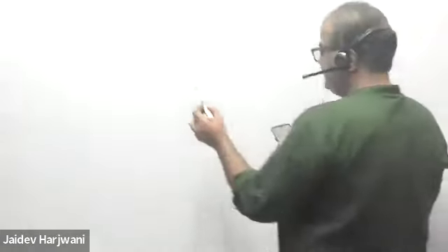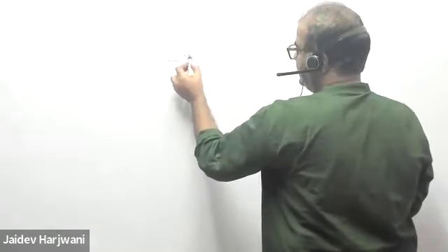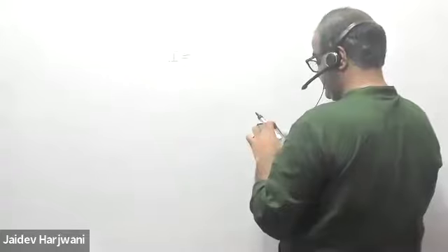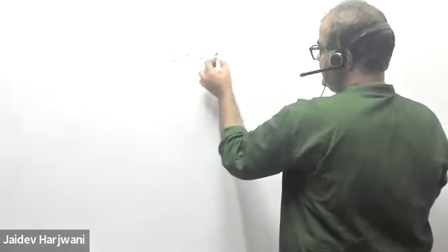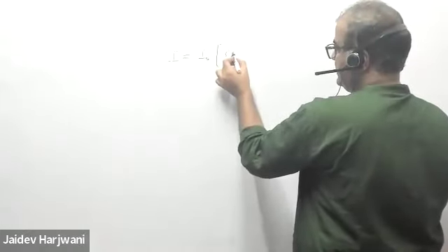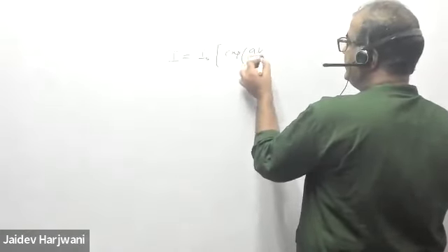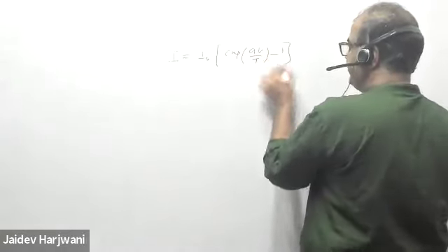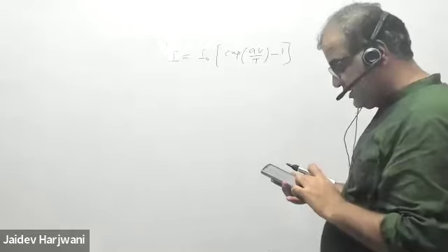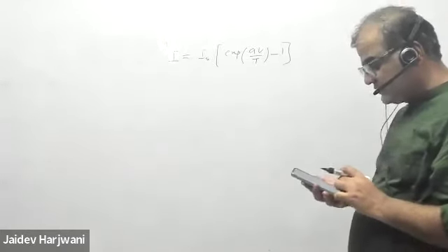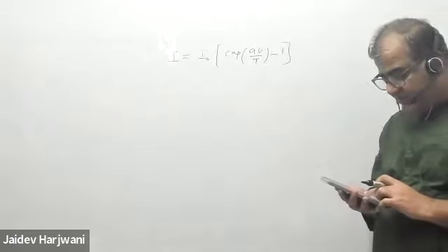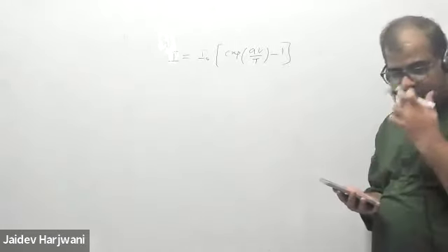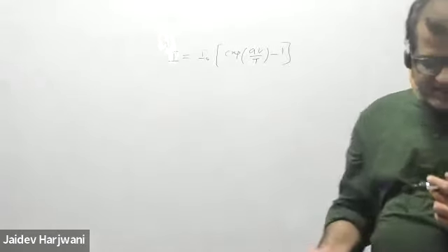Next question is: the IV characteristics of a device can be expressed as I equals to IS exponential (AV/T) minus 1, where T is the temperature and A and IS are constants independent of T and V. Which of the following plots is correct for a fixed applied voltage? So applied voltage is fixed.